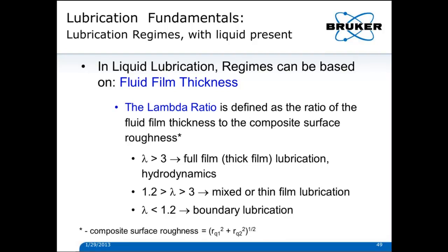This means we're sliding asperity on asperity, and we're either shearing a low shear stress film on the asperities, which is a boundary film, or we're shearing the material itself, and maybe plucking pieces of one material off of another. So when lubrication is too thin, or absent, we're in the boundary region, or what might be known as dry lubrication, which is a bit of an odd term.